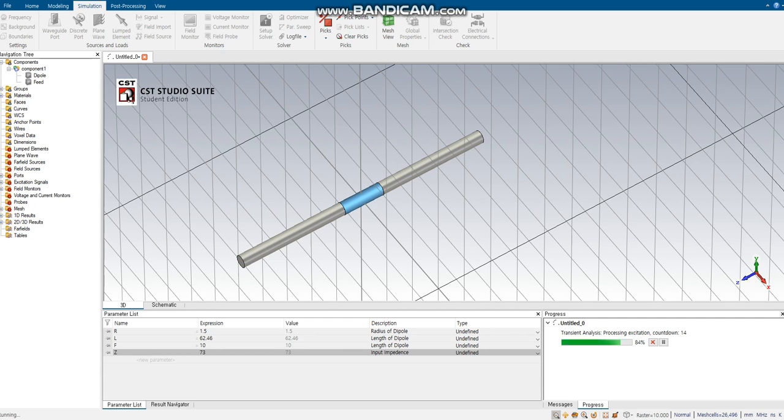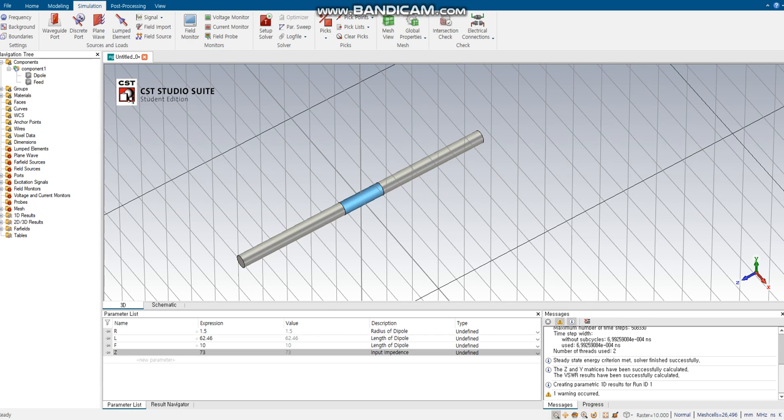So now let's design using CST. This is the first window. If we open the CST software, we will see this. Then we have to create a new project here, and choose microwave and optical. Then click on antennas as we're designing this. Click next. We are doing a planar antenna, so click on this.